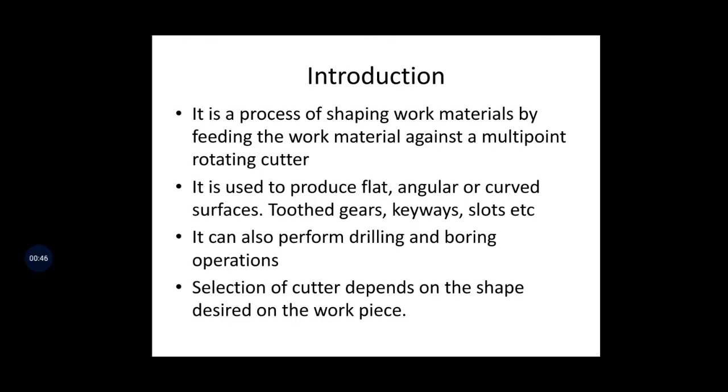If we want to cut a gear, we have to use milling. Using the lathe, you cannot cut gears. Using milling only, you can cut gears. If you want to make keyway slots, you have to use the milling machine. It is a process of shaping work material by feeding the work material against a multi-point rotating cutter.